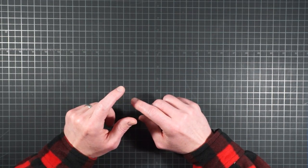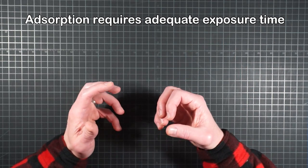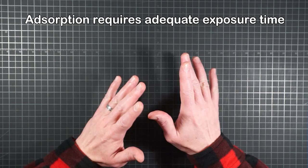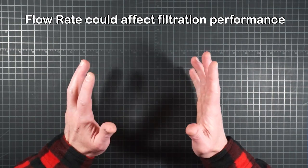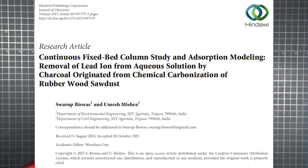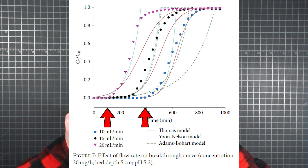In a filter where the water is constantly rushing by, it takes a particular amount of time to grab passing molecules from the flow and secure them to an available patch of surface. Well, this has implications for the effective flow rate on a filter's removal performance. From an adsorption modeling study published in the Journal of Chemistry, this graph shows the effective flow rate on breakthrough time. Now, obviously, filtering water twice as fast will wear out your filter quicker, but it should only do so in about half the time.